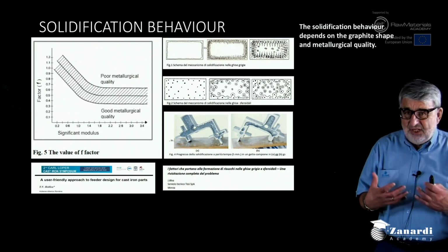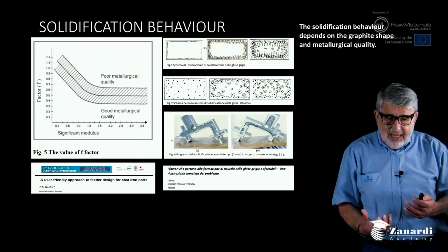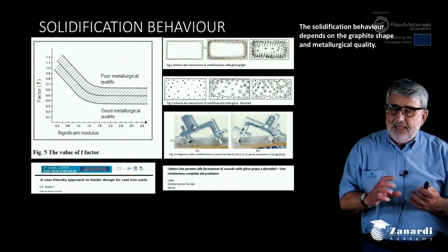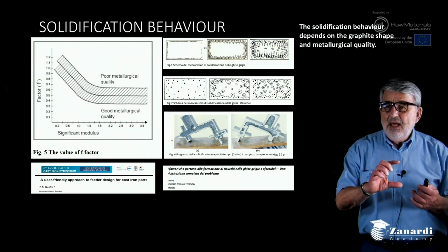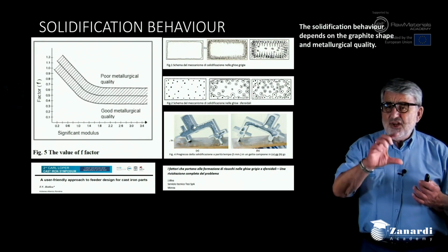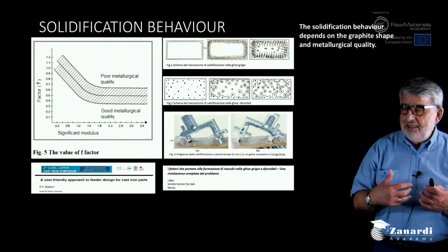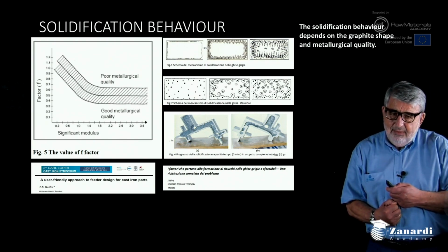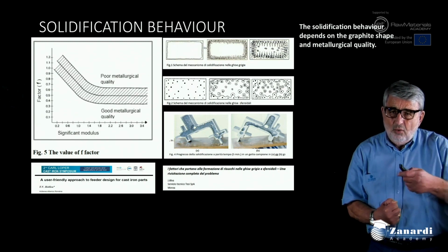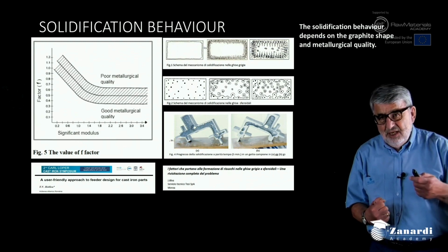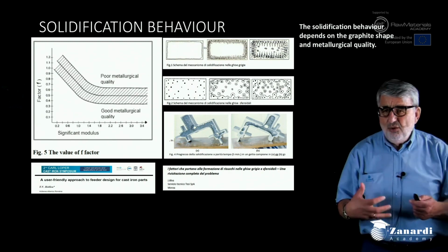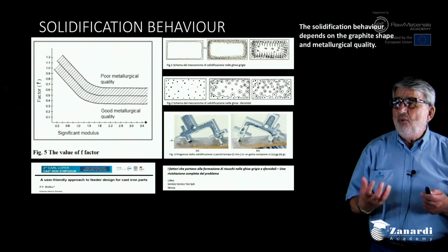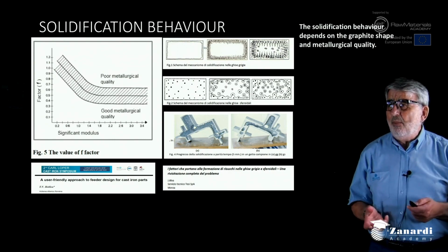This is called a massive solidification, with an expansion of graphite that in a short time makes a high pressure increase inside the freezing metal, which puts pressure on the mold walls that can be enlarged. And this is a source of porosity that we can find in the casting, and we need to avoid it by proper risering.